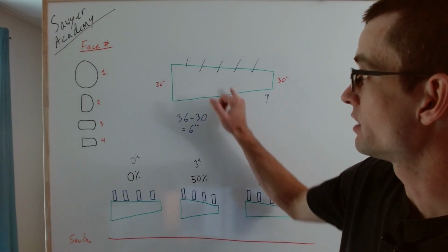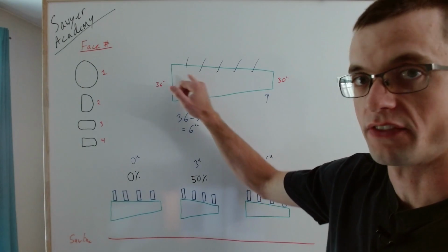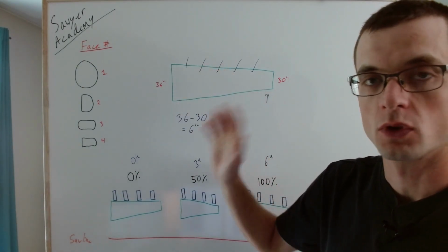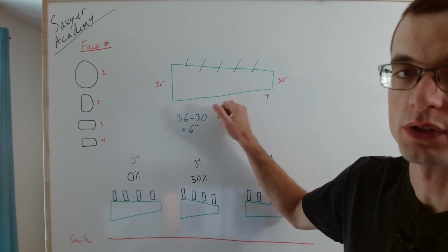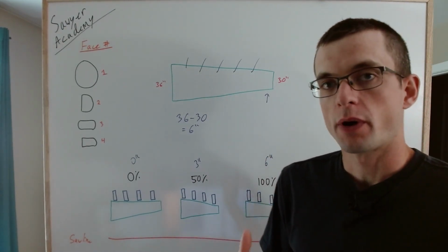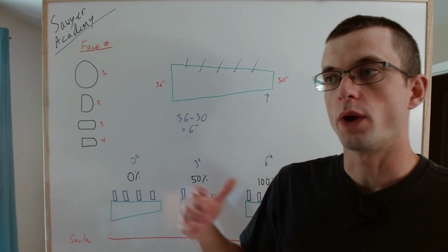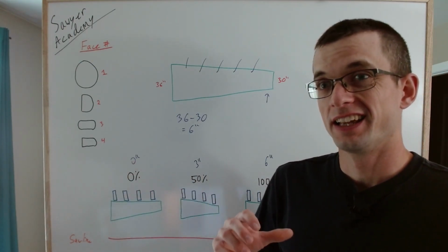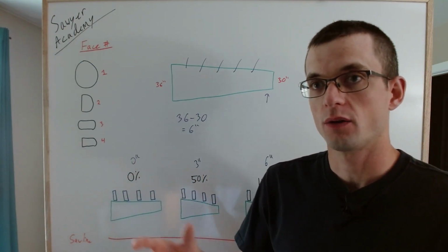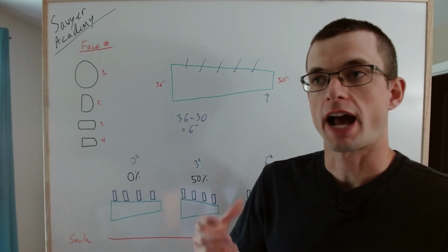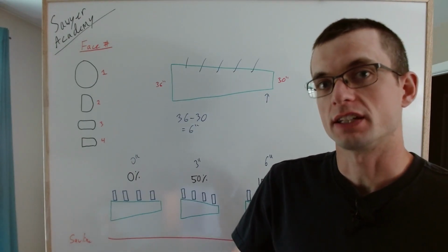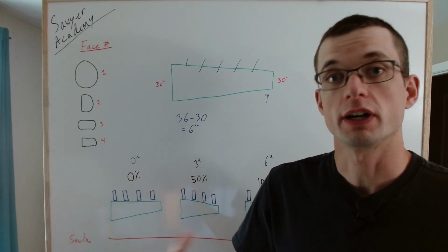So in this situation, we don't really care what this grade is. If this is going to be number 3 or number 4, who cares? If this face is all select and number 1, we want the most out of that. The hard part in commercial sawmills is when the logs come off the debarker, it's hard to tell where the limbs are without stopping to really look at a log. And in a high production application, you don't really have the time to sit there and rotate and look at the log.